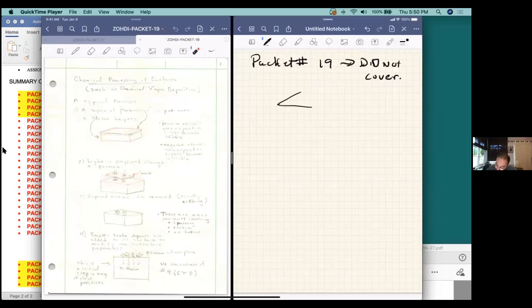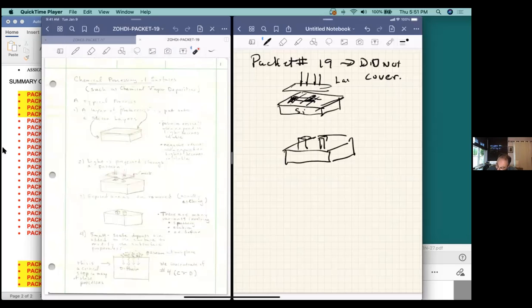So integrated circuits, basically, they start out usually with some kind of a silicon substrate. They then put some kind of a pattern or a mask onto the surface. They make all kinds of different configurations of these surfaces and so forth. And the basic idea there is that by taking a series of masks and a series of laser applications, you can start to build up rather incredible electronic circuit boards and structures by simply building onto a silicon substrate. You can use intermittently lasers and layers of epitaxial gas, which basically builds up these layers.